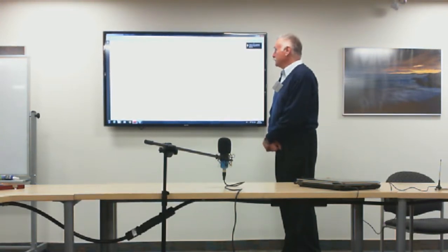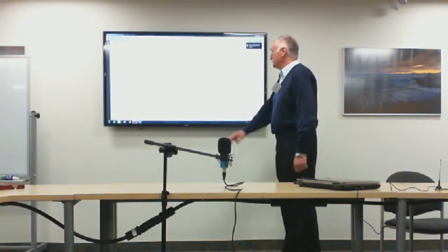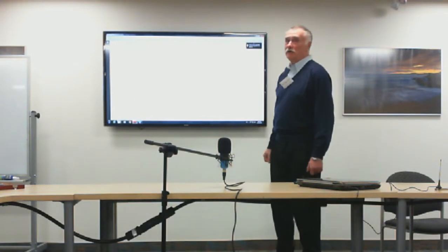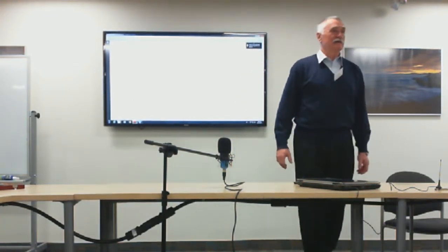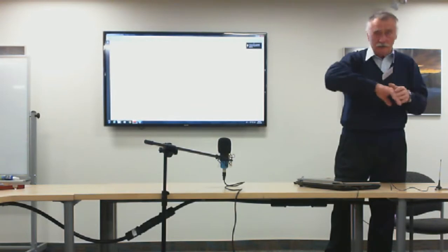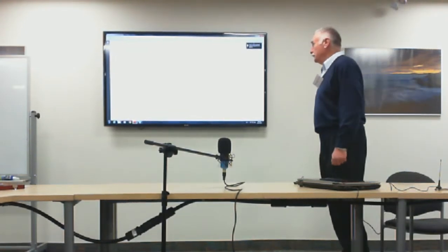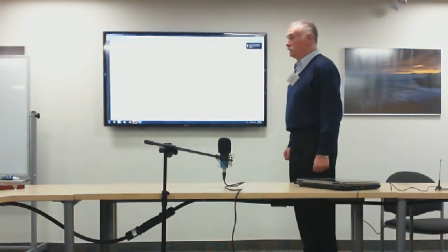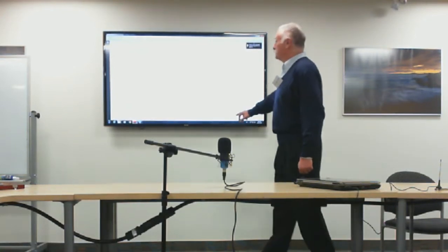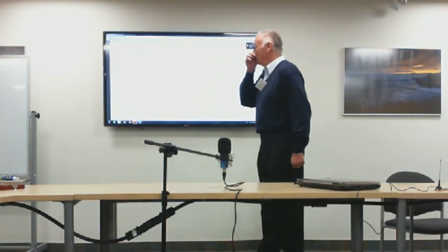The amplified electrical signal must be converted into sound waves. Of course, then we need a loudspeaker or headsets. Headsets are often more advantageous than loudspeakers because they seal to your ears and lock out the room noise. So for weak signal work and reception, you need headsets. If you receive a great signal, then speakers would do. Receiver terminology up, please.